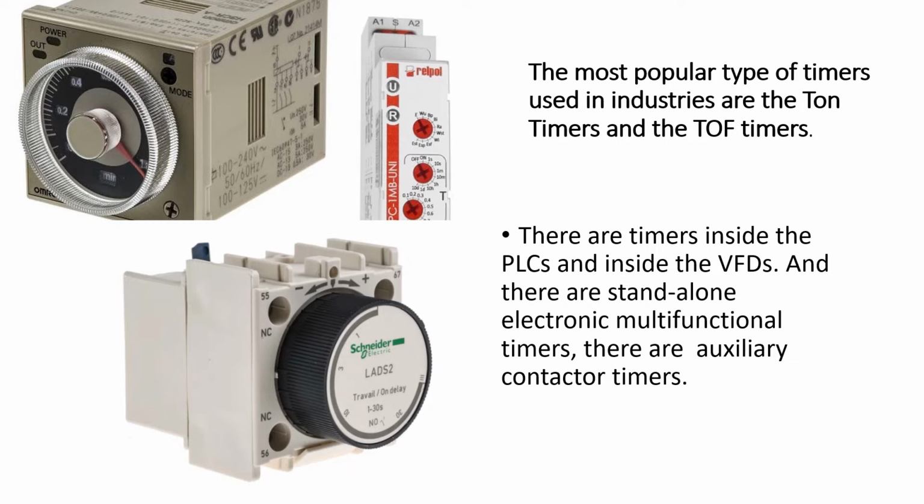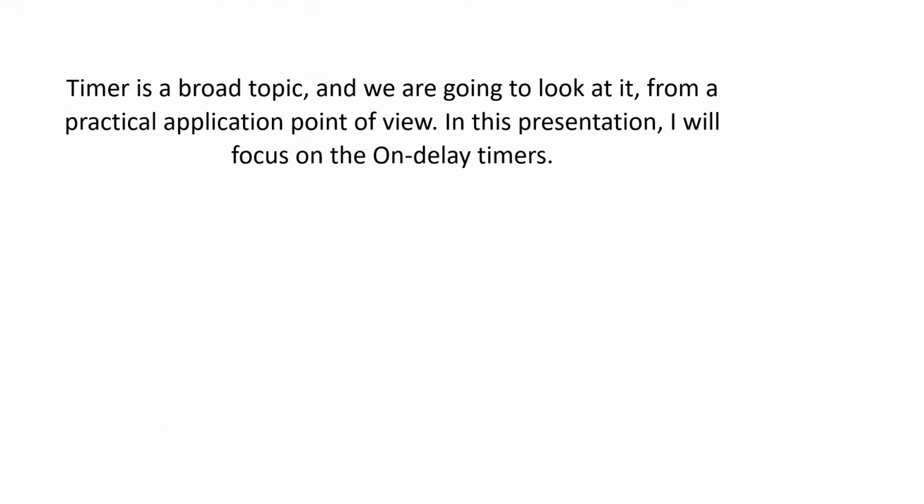For the turn-off timers, when voltage is removed is when they switch. They actually put on the load. This is very useful, and it is mostly used with auxiliary contactor timers. So there are also timers in PLCs and in variable frequency drives. And we have standalone timers like the timers we see in this slide.